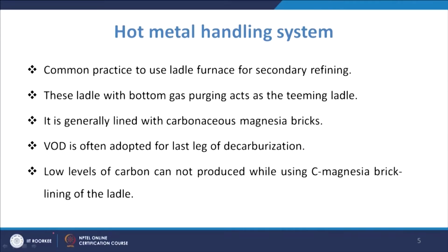Now, the tundish is the vessel that comes after the ladle. The tundish receives the liquid metal from the ladle and then distributes it, passing that liquid metal to the mold. So, the tundish is necessary to teem the steel from the ladle to the mold. It acts as a buffer vessel between the mold and the ladle.